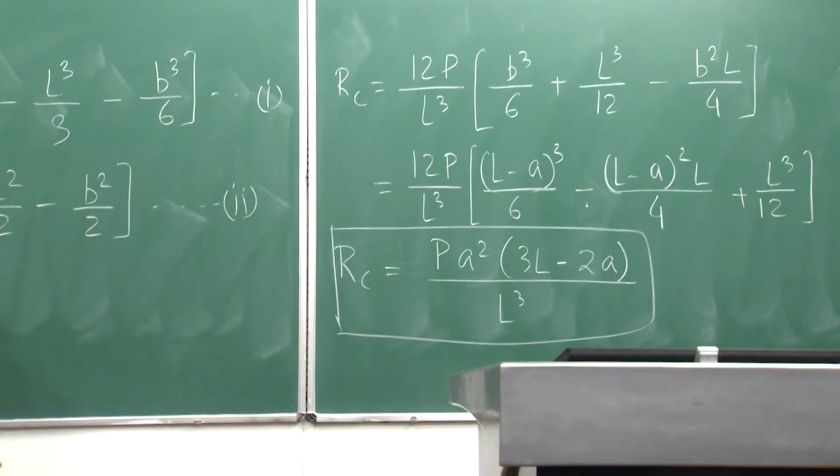Already we have got this expression by using method of superposition, right? The same thing we are getting by using Castigliano's theorem. Only thing is that you just replaced the support by providing the proper support reactions, and then finally you made delta C and phi C equal to 0.